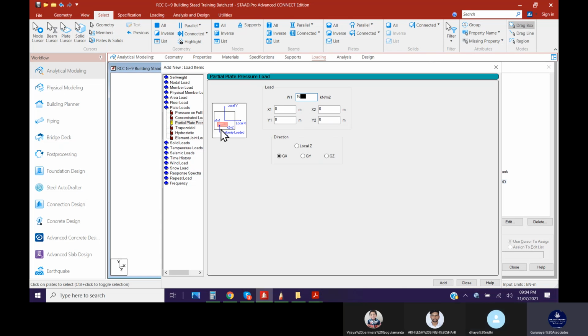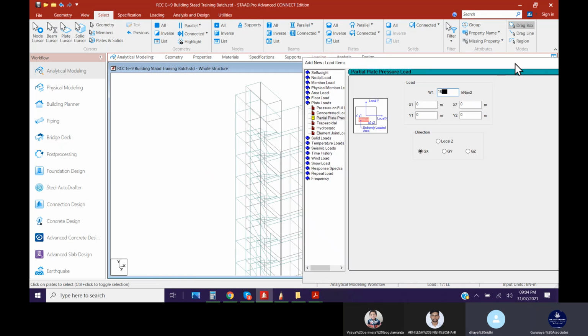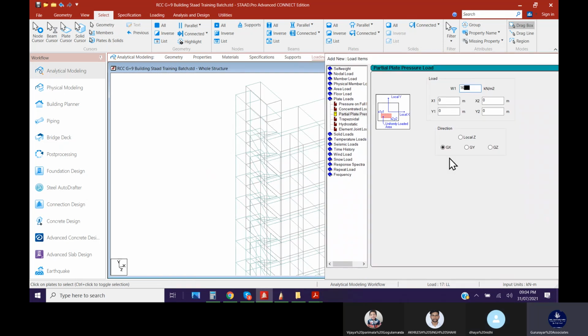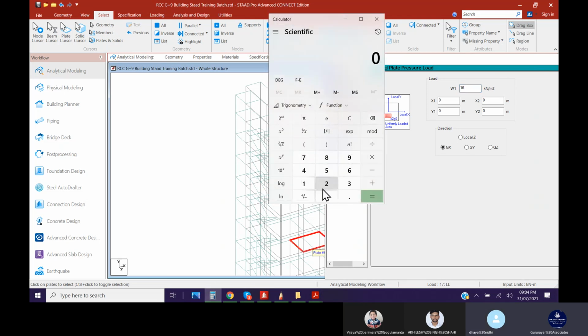So from here, let us say the wall width is 2.5. In this 2.5, in the center, let's say there is the 125 mm. So that means 2.5 minus 125 mm. 2.5 means 2500 mm minus 125 mm, divided by 2, for both sides.